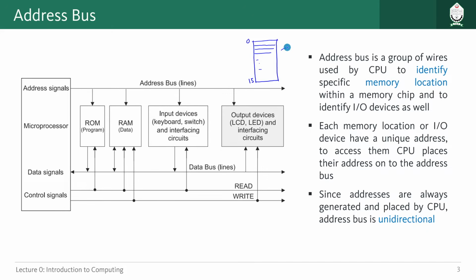So basically that was a 16 by 8 RAM, right? So we could actually address different locations here, that means different rows here, using the help of the memory address register, if you remember correctly, right? So we could actually point to a different location here, a different row here, and try to fetch data or write some data there in that row.